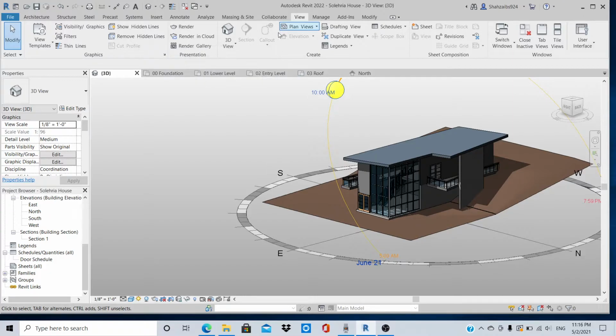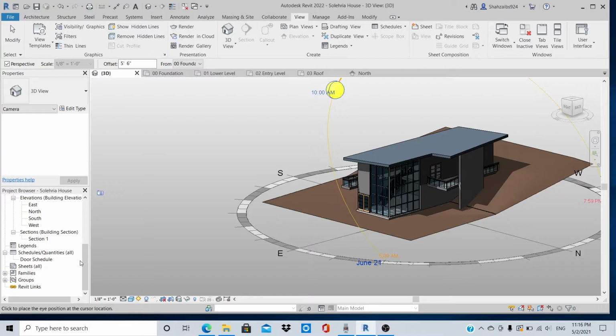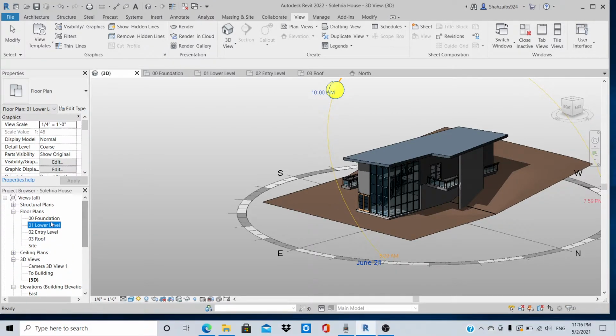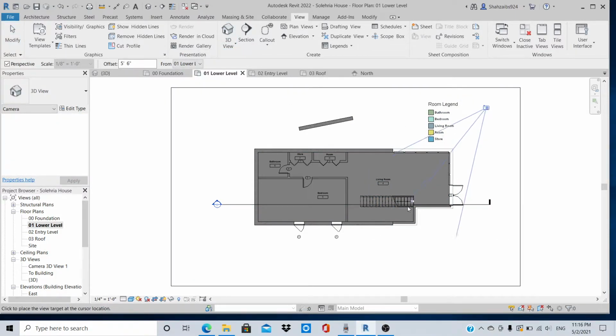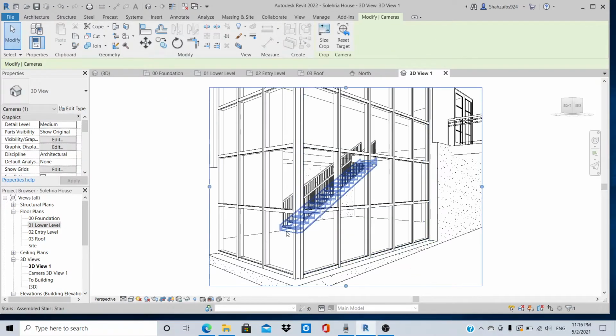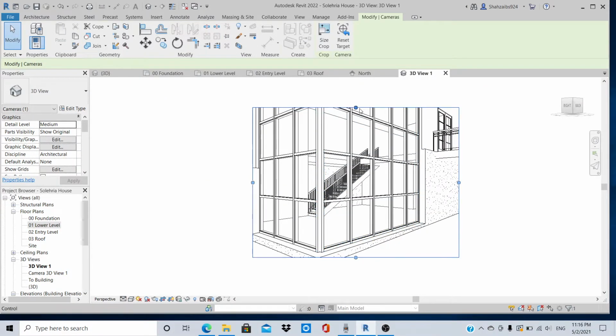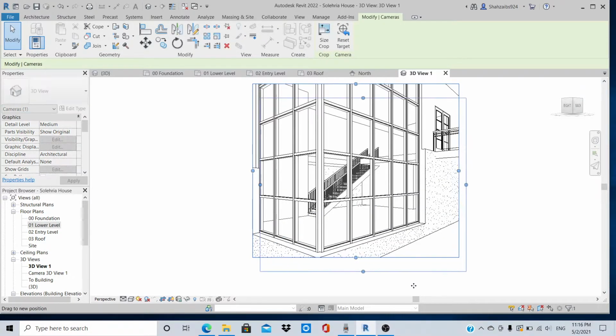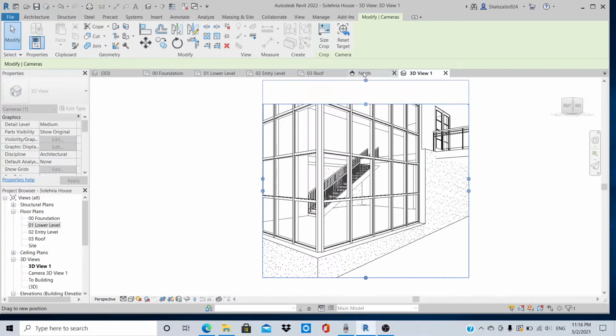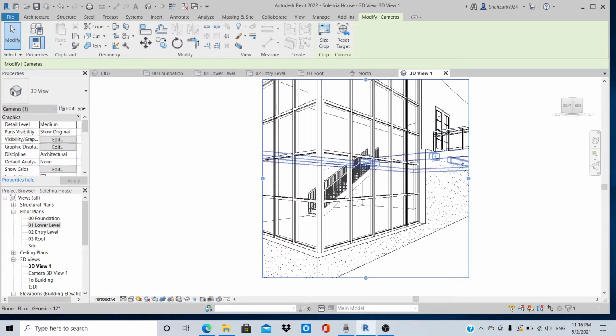And to get the camera angle, you have to click 3D view and click camera, and then you have to go to foundation folder 1, and then get the camera out. Well, you take a picture, and then that's what you get, and the camera you can adjust and stuff to see what the house would look like on the ground, which is very insightful.